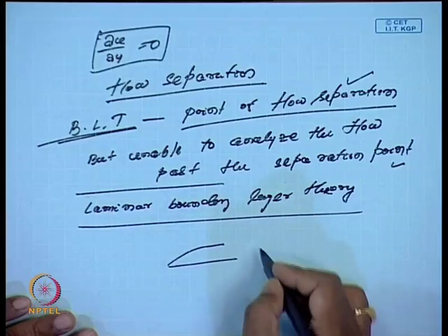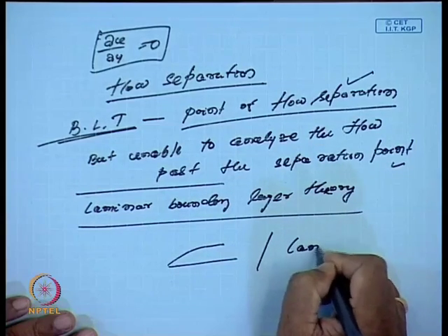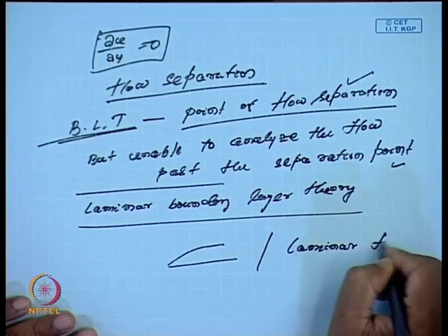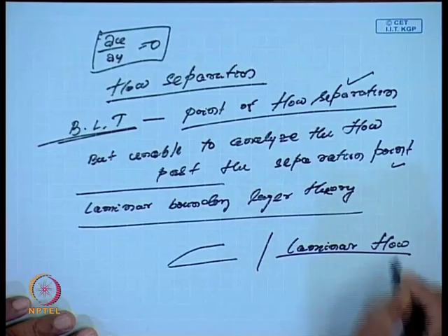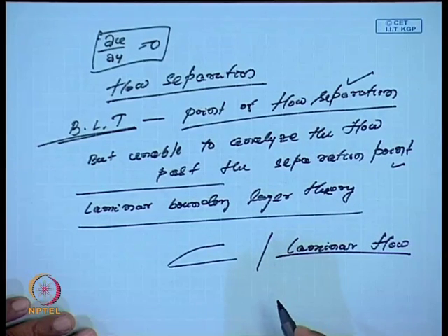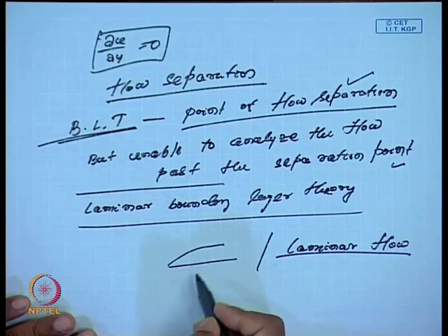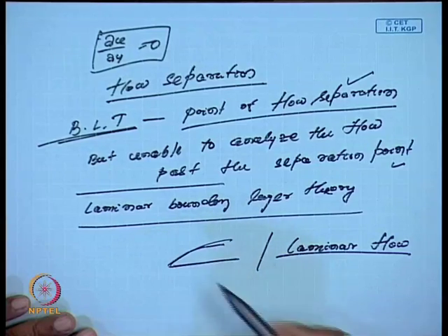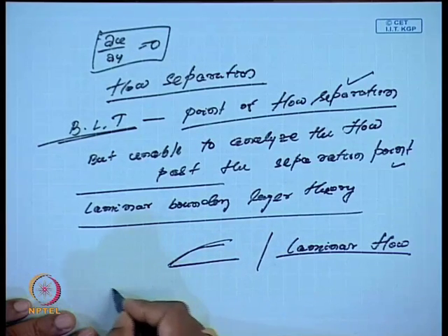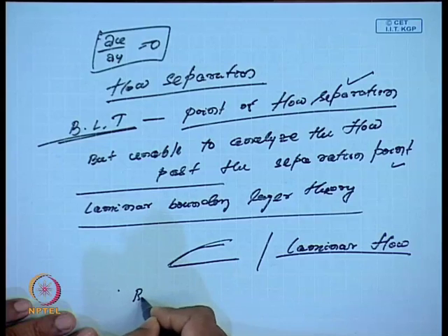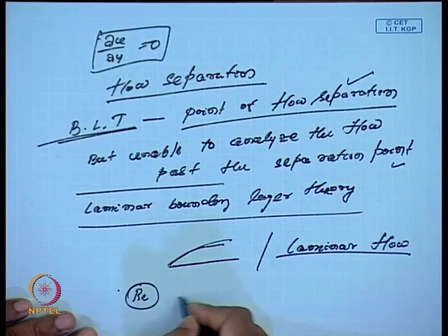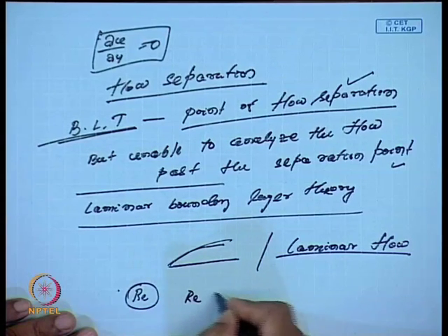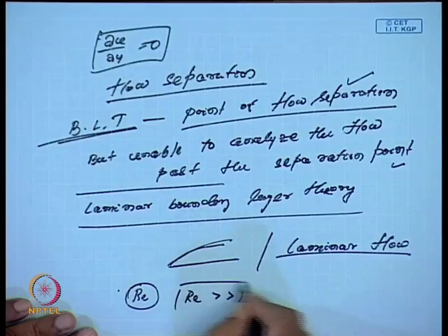On the other hand, we have also talked about laminar flow for unidirectional flows, at intermediate Reynolds number, but in case of very large Reynolds number, laminar boundary layer theory holds good only for a class of problems. And beyond that, when the Reynolds number Re becomes extremely large,